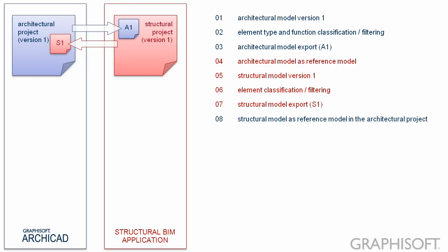8. Architects merge the structural model into their current project. Filtering is available for the import, and imported elements can be placed onto specified layers. By default, the new imported elements will be protected in accordance to the reference model concept. Architects may compare the two model types as two view sets. One contains the architectural model, and the other contains the imported structural model. Architects query the profiles and materials decided on by the engineers.